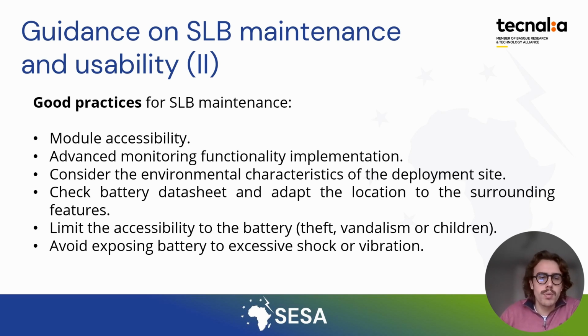It is very important to maintain module accessibility in case of single element damage of the battery. Additionally, advanced monitoring system implementation is key to avoid premature damage of battery systems. As to environmental aspects, it is very important to adapt the place where the battery will be installed to the datasheet environmental characteristics provided by the manufacturer. Additionally, it is important to avoid situations of excessive shock and vibration for the battery, and also limit the accessibility of third parties to this system.